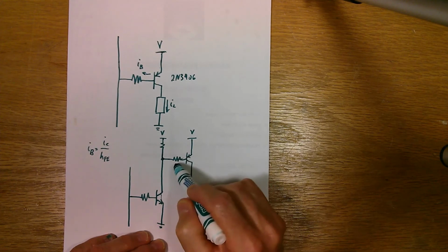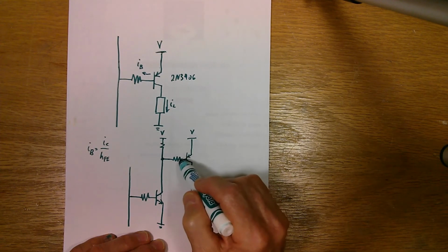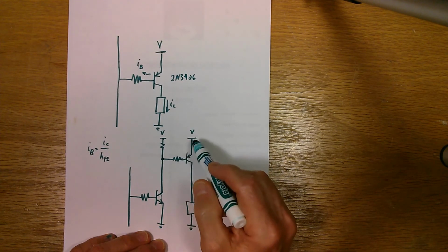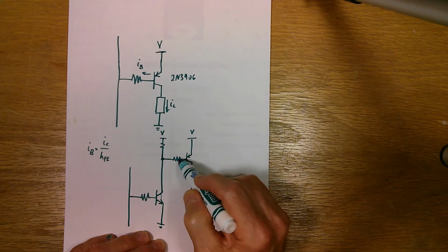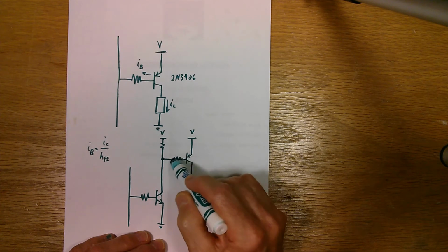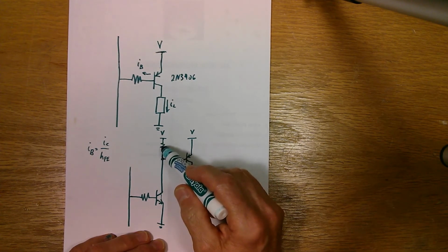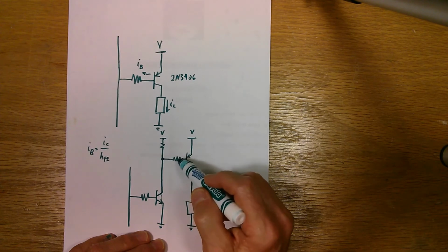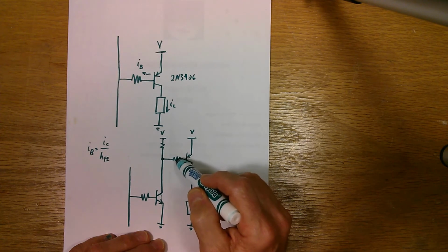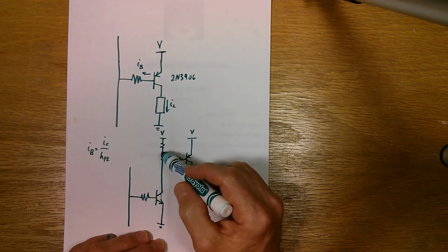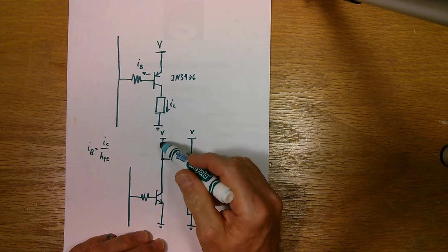So the value of the base resistor here, if the supply was 12 volts, would be a certain value. And if this was 5 volts, the resistor here would actually be smaller because you have less voltage drop across it in order to get that current flowing through. And this resistor here, you've got to make it small enough that it's going to be smaller than this one here, but not so big that you have too much current flowing in this transistor here.